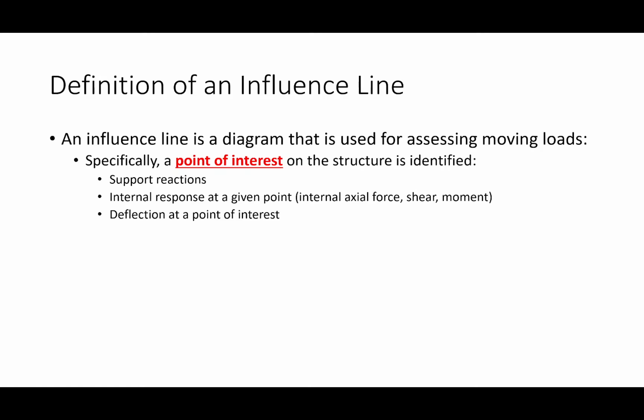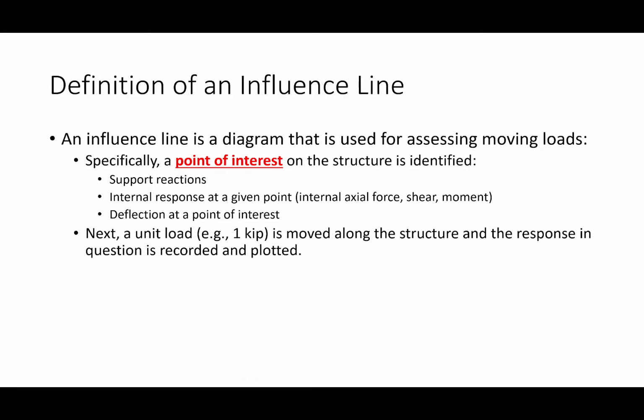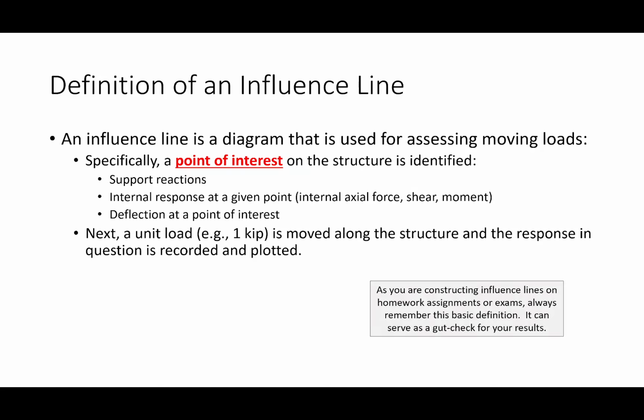Once I pick that point, I take a load and I move it across the structure. What load do I move? Well, traditionally, you will move a unit load. So think of it as like a 1 kip load that moves across the structure. And as that load moves across the structure, we will record the response.